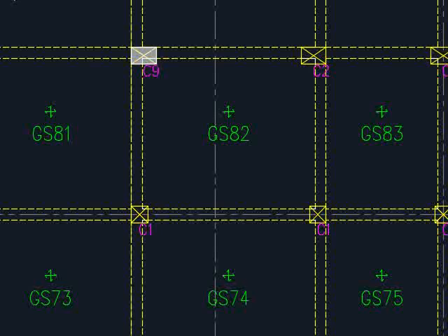When you do the classifications, the safest approach is to round up the amount of reinforcement bar so that the design becomes more conservative. It is not for you to round down the amount of reinforcement bar to make it more economical. This is to prevent a situation where you overlook something and under-design the section.